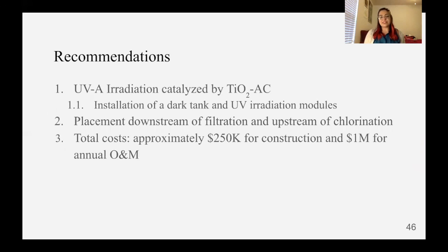So our recommendation will be using this UVA irradiation catalyzed with a titanium oxide activated carbon composite. And we'll do this through installing a dark tank and UVA irradiation modules, placing it downstream of filtration and upstream of chlorination, with a total cost of about $250K for construction and about $1 million for annual operation and maintenance.